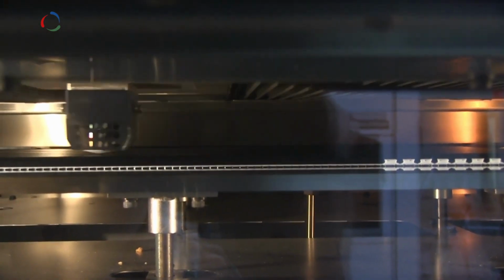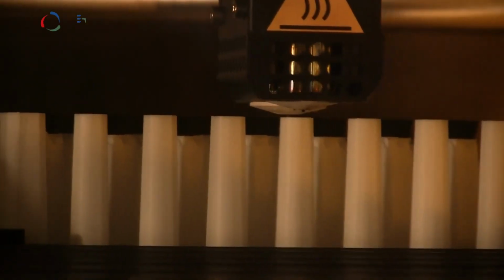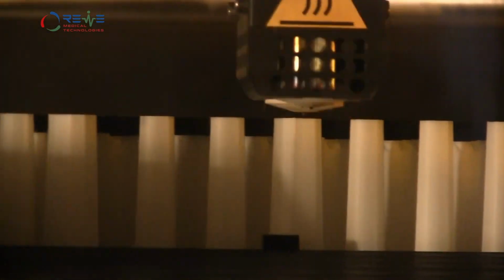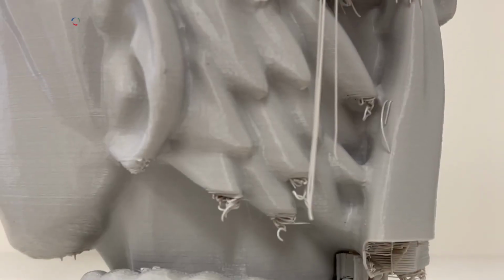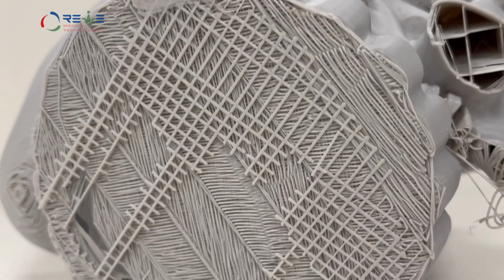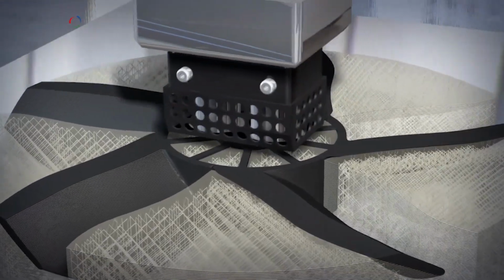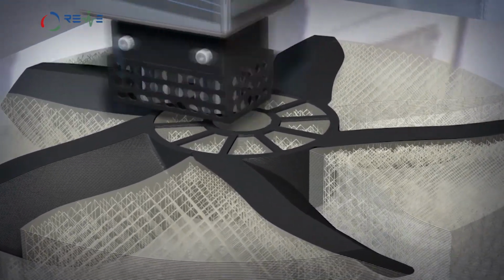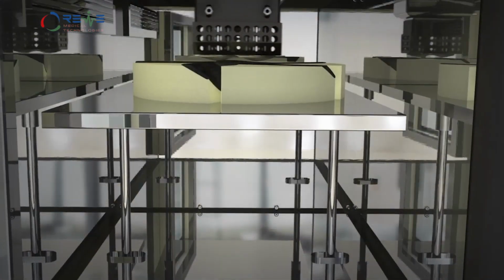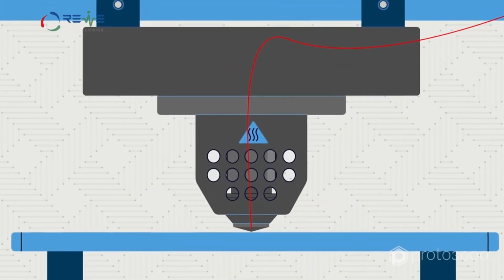Over here, you can have single nozzles or multiple nozzles, which can be used to make different types of structures. But there are a lot of limitations in this 3D printing process, especially overhanging. When we're making an object and it is overhanging at some point, and there's no support underneath it, it will just fall down. So we need to add a lot of supports in this process. When building, you have to be very careful about what type of design you're printing and what sort of orientation you put it in. There are a lot of limitations in the previous ones as well, but this has the most limitations in terms of processing.